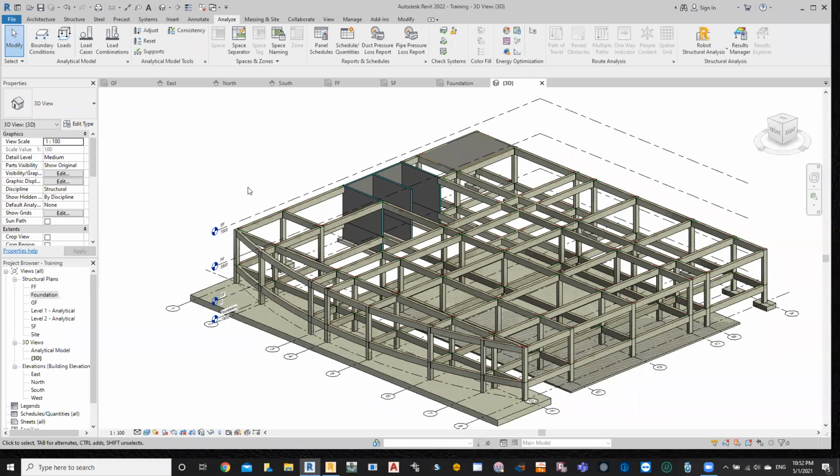Okay. Mister, I remember in the beginning of the class, you told us we should design the slab in Robot, not in Revit. Yeah, to model it, if it's irregular. Like a sunken slab or a weird shape? No, sunken slab does not matter. Eventually you're going to draw it as a regular slab. The difference between a sunken slab and regular slab is the loading and how it's constructed in reality. But when it comes to designing it, when it comes to modeling it, both of them are the same.